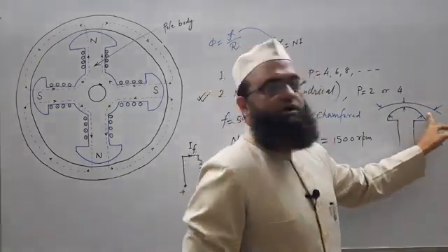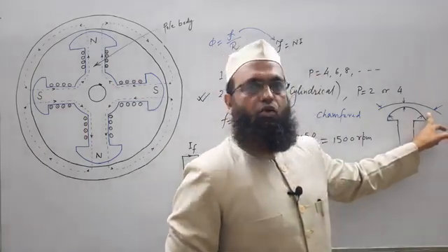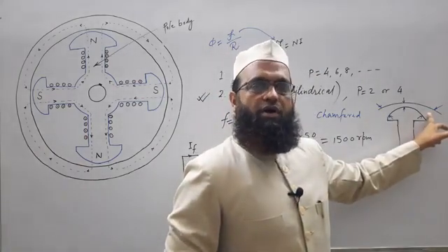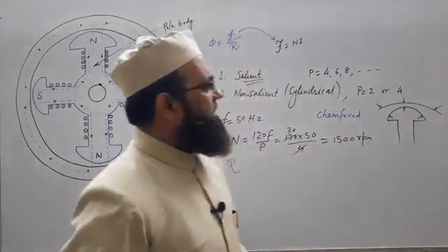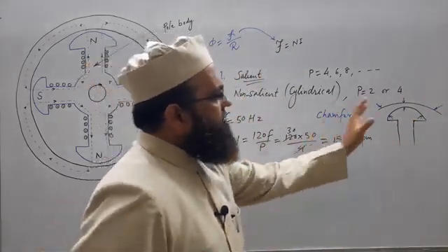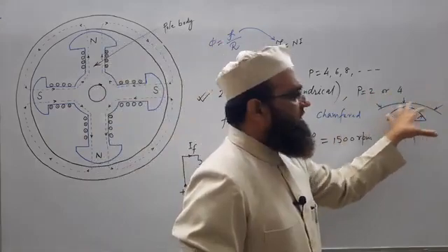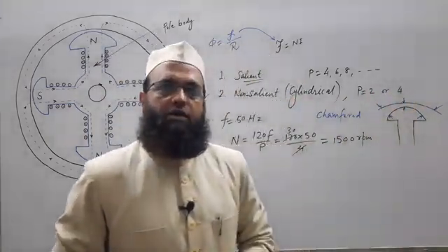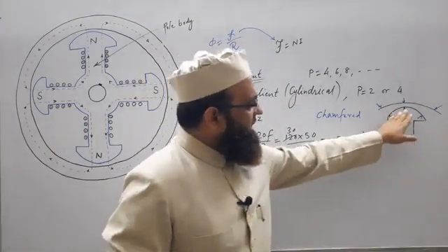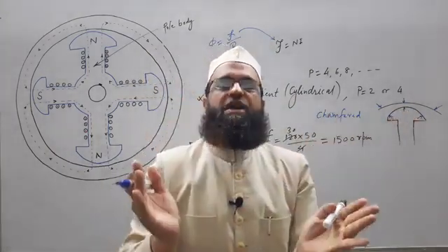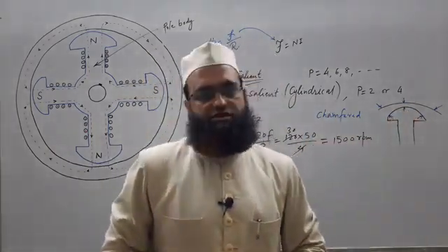And the position where the air gap is more, reluctance will be more, hence flux density will be minimum. So we can say that we now have a varying flux distribution, not constant. And you may further observe that for this shape, that distribution has a sinusoidal nature.